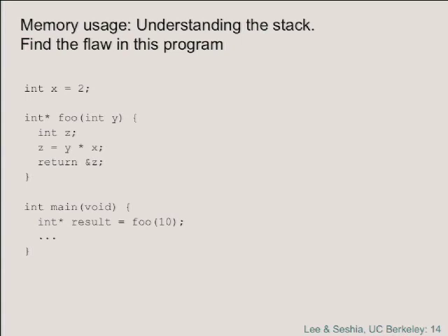But the issue is that at any time, a C program can get interrupted. And what happens when it gets interrupted is your current location of the program counter gets pushed onto the stack. By the way, that'll probably overwrite the value 20, immediately. And then any registers that the interrupt service routine uses also get pushed onto the stack, their value. And then an interrupt service routine executes. And then all those register values get read back off the stack and put back into the registers. And then the program counter gets restored, and then you resume executing where you left off.